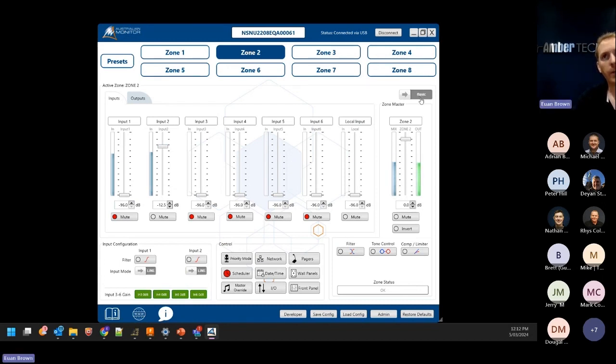If you have then set up the configuration and you want to prevent the user from making too many changes to the mix, for example, if you adjust the volume too low, you can turn on this advanced setting and it brings up these settings of max and min values. So you can set that to a minimum value to prevent end users from muting the system, for example, or the max level from making the level too loud. So that's how you set the restriction for the end user in terms of the volume controls in the mix.